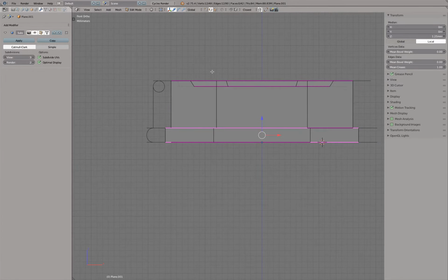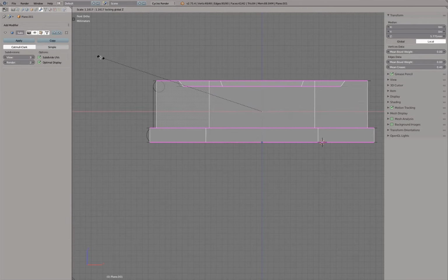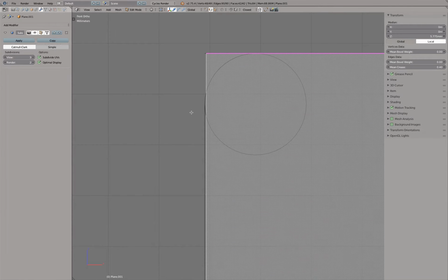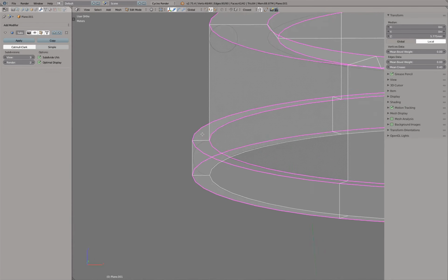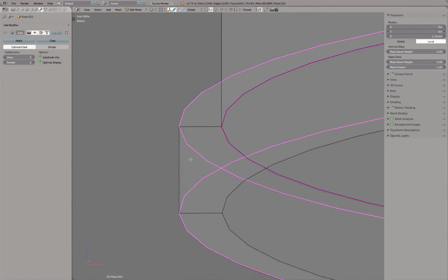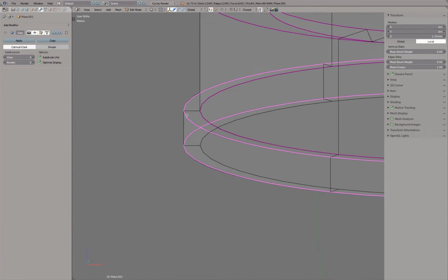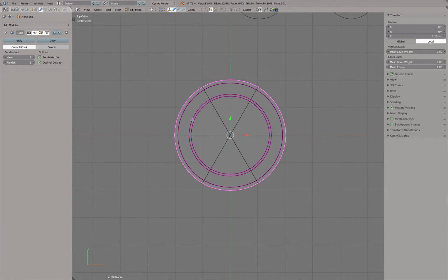Go into edit mode, AA, so I select everything, and then I press, make sure that this is set to boundary box, S, Shift Z, and then actually I scale everything away from the Z center till, for example, it hits the proportions we actually set up first. And there we see, here we might have to S and Shift Z, scale those back a little bit, or tick. Okay, good.